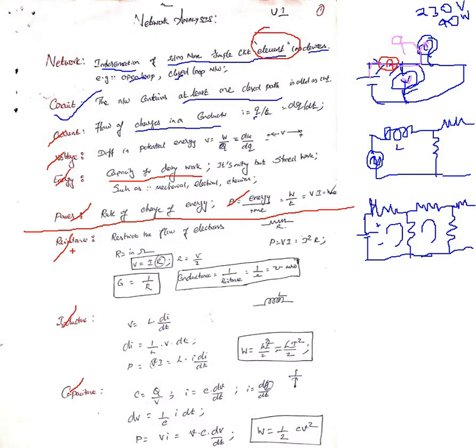The first element is resistance. What is resistance? Resistance normally opposes the flow of current. That is its general function: it opposes the flow of current. See here, this circuit has an incandescent lamp directly connected to the power supply, and the lamp is glowing. Before connecting the power supply, connect a multimeter across the lamp. The multimeter has an ohm, resistance, setting, so check the resistance value.